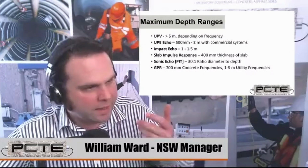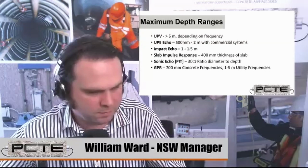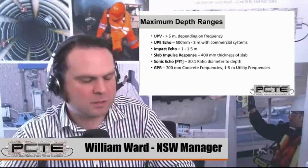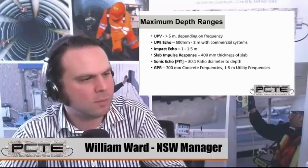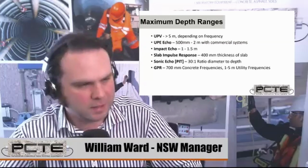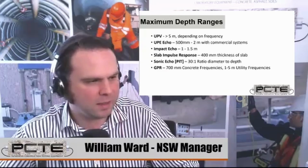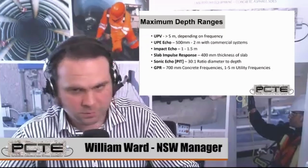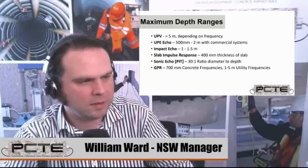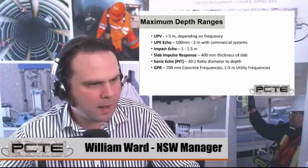The slab impulse response technique is very limited by thickness. Because we're hitting a flat plate of concrete and trying to get it to vibrate, we have a maximum of thickness where that stiffens it up so much it will no longer move under the hammer blow. And we'd call that around 400 millimeters. So if you're assessing if slab impulse response is appropriate, you wouldn't want anything greater than 400 millimeters, because that would control the test more than any structural support behind the slab.